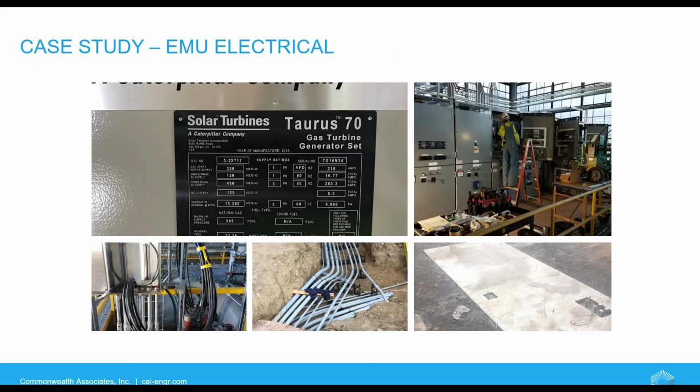So as we've talked about, the new CHP nearly doubled the electrical generation output from 4.5 to 7.8 megawatts. And this resulted in the need for electrical upgrades, both internally and also with the distribution from the heating plant to the campus. New equipment within the plant meant new MCCs. They had to upgrade other MCCs to accommodate the larger generator and other equipment. Additionally, cabling was added to handle the increased output, along with new controls in place to handle operation in island mode, along with potential black start scenario.